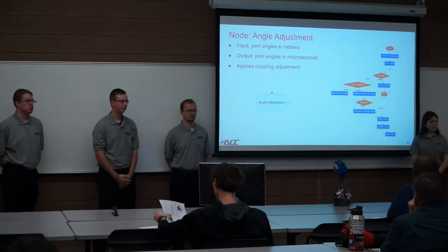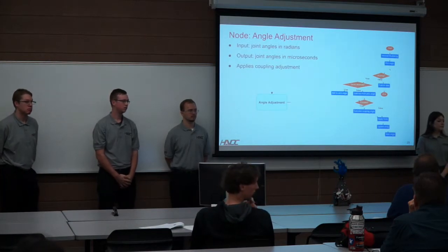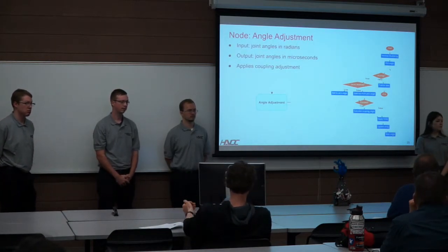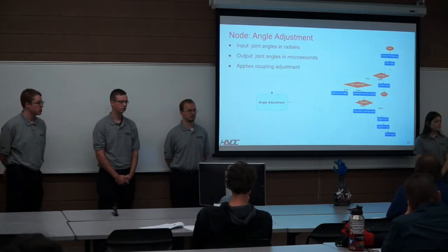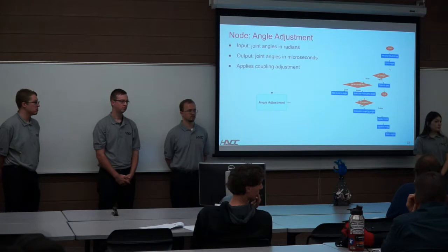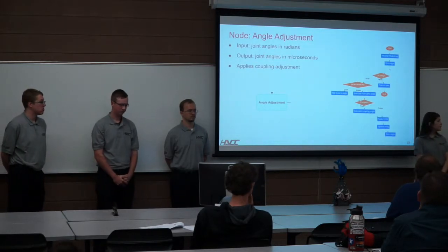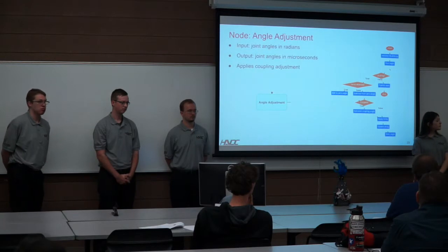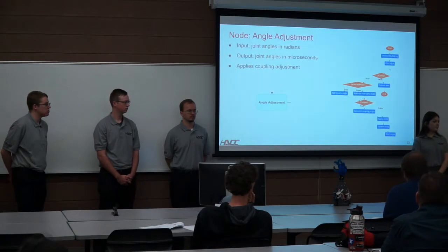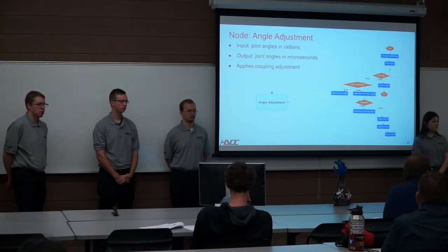Okay. Thank you. What was your intention of the haptic sensors? Were you just going to detect the force applied, or were you going to try to provide feedback to the articulated hand? That's a great question for Sandy. The idea was to be able to detect when we were actually grasping something, because if you don't know that, you could drive your fingers together even if there's something in the way. So the idea was to prevent the system from breaking itself. If we went a little further, we could maybe implement some sort of haptic feedback control, but again, that's expanding our scope, which was already big enough.